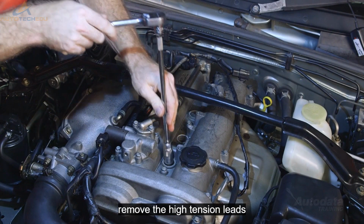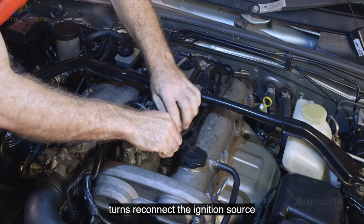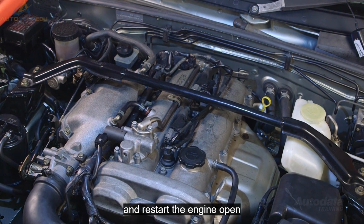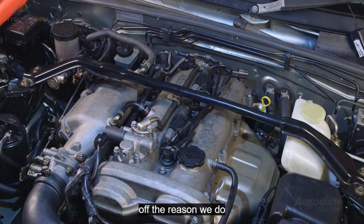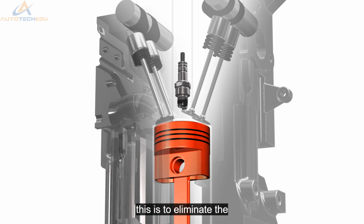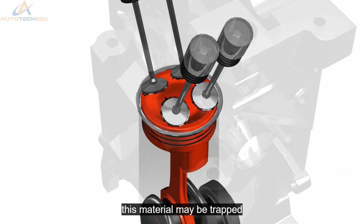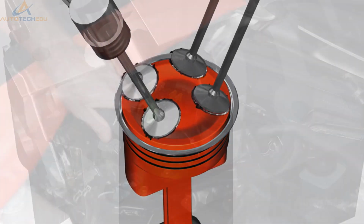To begin, remove the high tension leads or coil packs and loosen the spark plugs a few turns. Reconnect the ignition source and restart the engine. Open and close the throttle a few times and then switch off. The reason we do this is to eliminate the chance of any foreign material being dislodged by the removal of the spark plugs. This material may be trapped between the valve and valve seat, causing an incorrect reading.